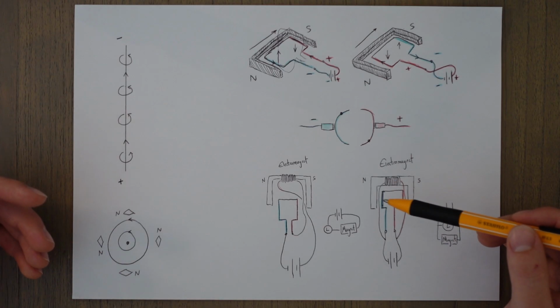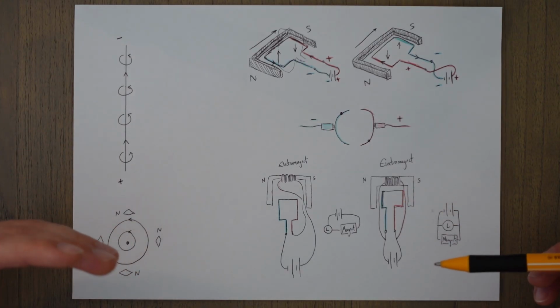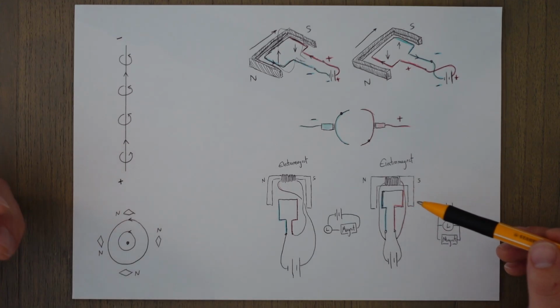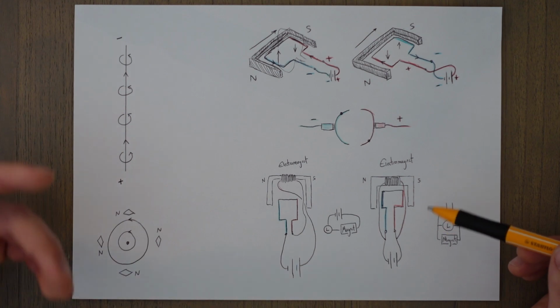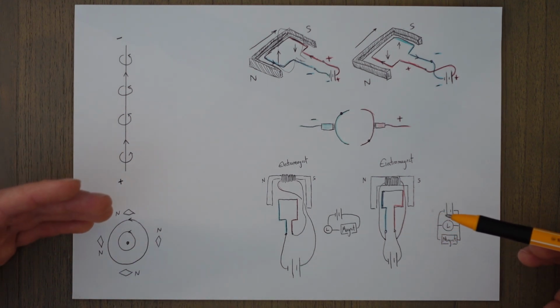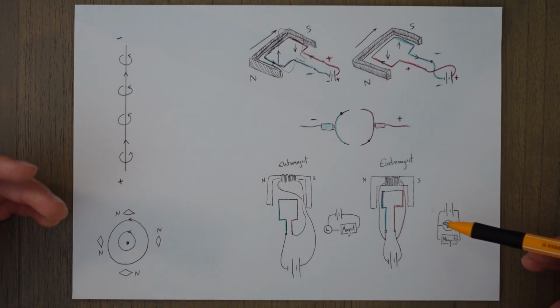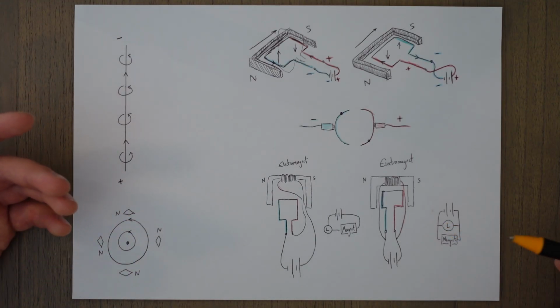In contrast, we can use a parallel setup, which is often called a shunt motor. This uses a high resistance for the stator magnet, which causes quite a low current flow. That means a weaker magnetic field and a lower torque turning force, but it has the benefit of a constant speed because the difference between the two magnetic fields is not that great. This type of arrangement is for things that require a long sustained output, like a fan for a ventilation system.